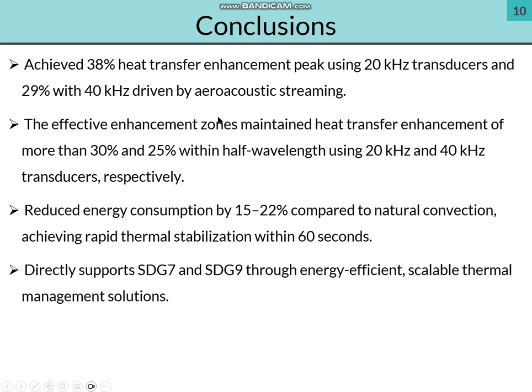The next is the conclusion. The ultrasound enhancement of heat transfer for the 20 kHz and 40 kHz could improve the performance by 28% and 29%. The effective enhancement zone in both frequencies was within the half wavelength range from the center of the heating surface.